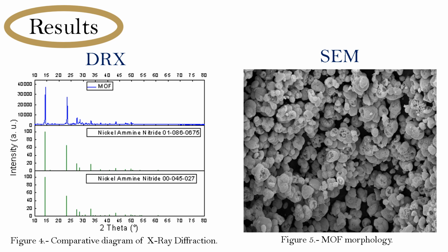Figure 5 shows a photo taken of the material at a magnification of 20,000x at 20 electron volts. Not having a large grayscale, it can be said that there is a certain homogeneity of the compounds in the synthesized material, in addition to having spherical morphology.